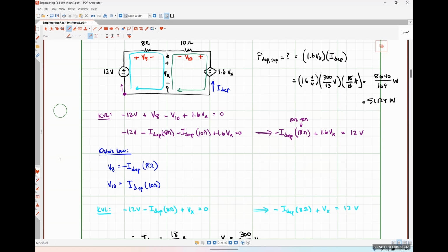Who cares? And I mean that specifically because how did we define voltage on Friday? Potential difference between 2 points. Are those two different points? So why can't there be a voltage across those 2 points? That's literally all the voltage is, okay? So having voltage drops across open circuits is 100% fair game.